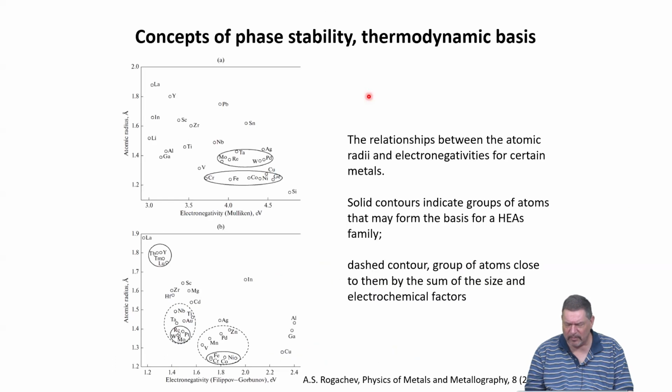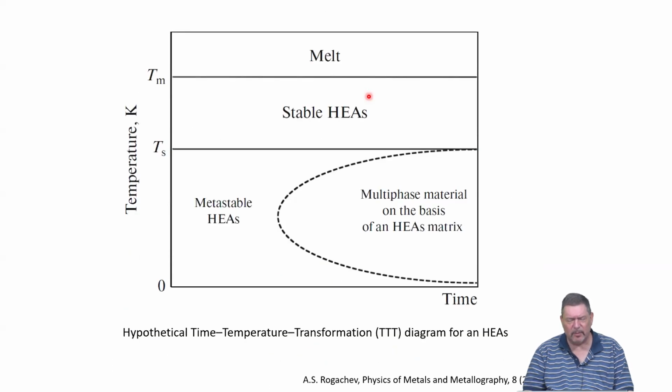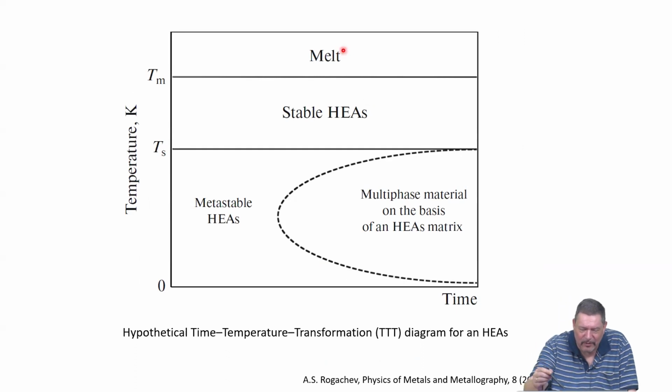they all calculate at the melting temperature, and that's a big problem, because when you come from the liquid and you cool, you go through a region where the temperature obviously is high, while the crystal is the stable phase. A high temperature means the term temperature times entropy is large, and it's highly likely that this region of higher temperatures is giving you conditions where a solid solution phase might form.